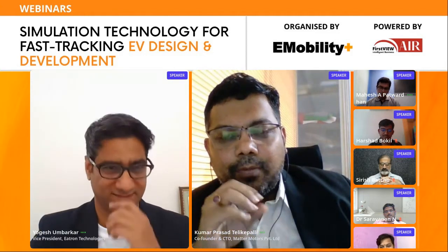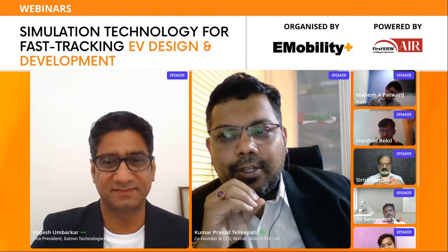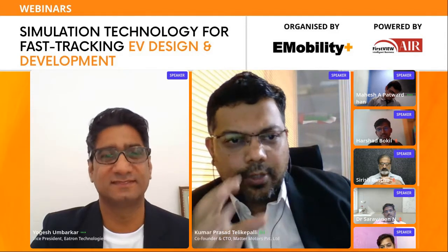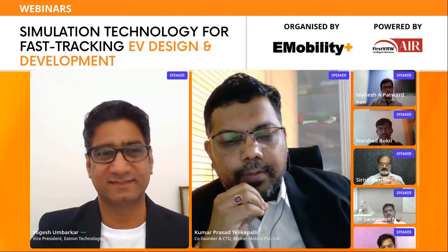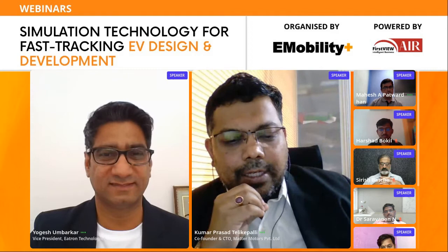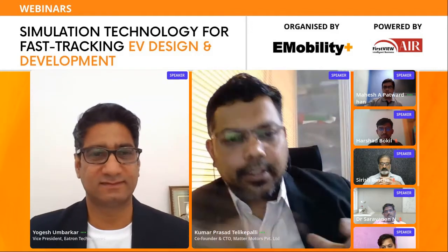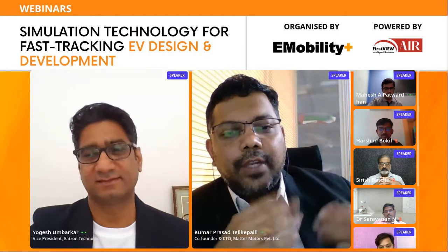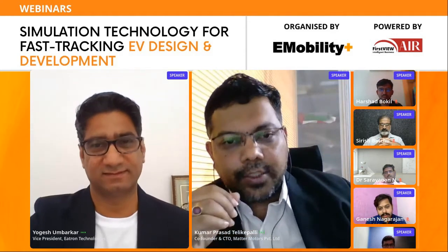I think not many people really relate to it, but most of the people who have looked at the data of what's happened in the last 2 decades, be it hybrid powertrains or even on the EV machines, will see that the RPMs of the electric machines are getting higher, and there's a great demand for you to get into a field weakening zone, which enables you to operate at higher speeds.